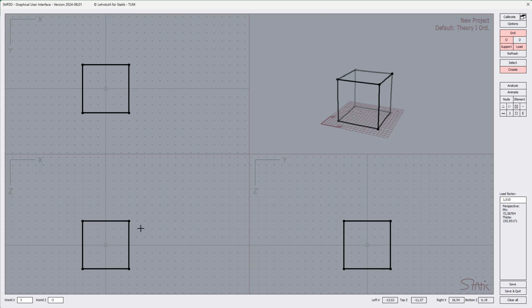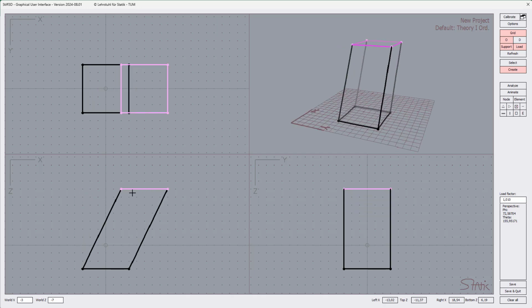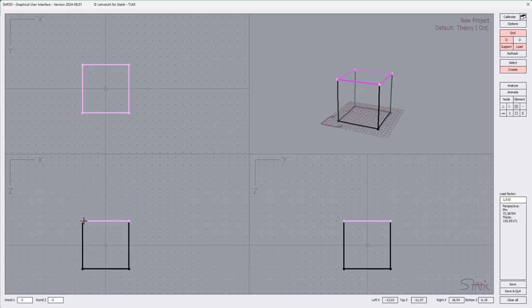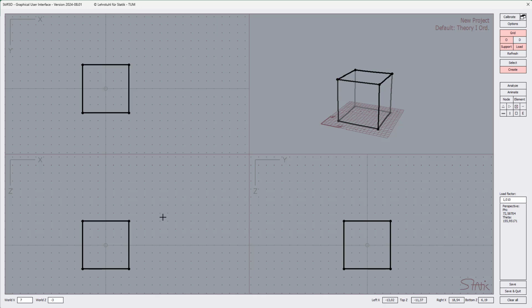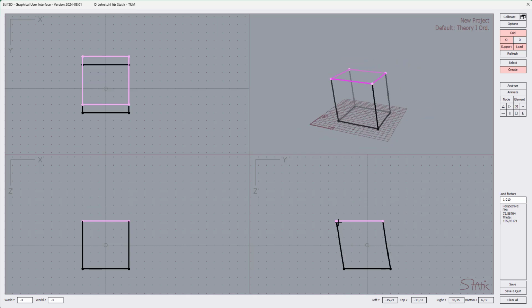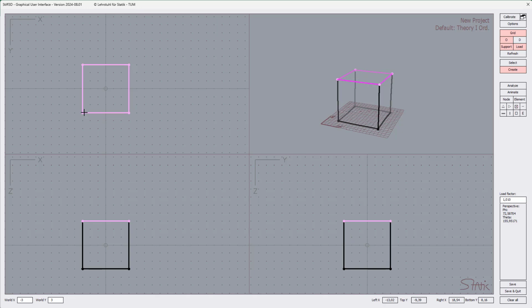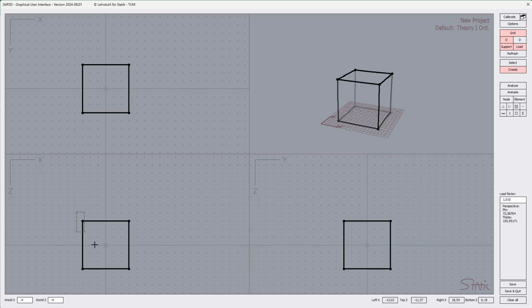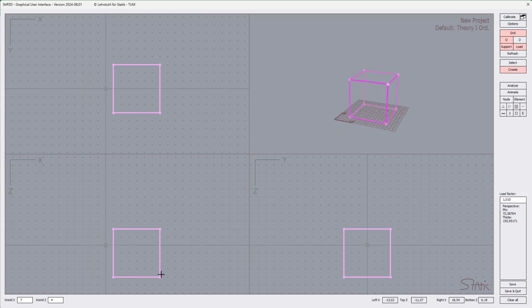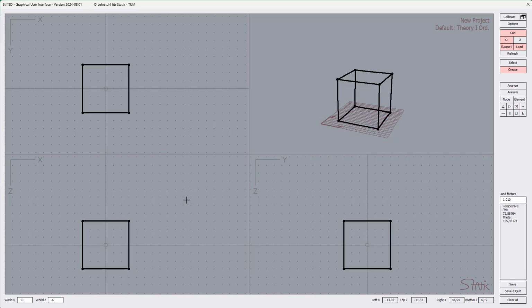We can of course select more than one node by the rubber band, and if we now press the left mouse button again at one of these nodes, you see that we are now simultaneously moving all of these selected nodes, and we can do that of course within all of the other views, or just proceed here as an example. So by that we are able to move the object into the place where we would like to have it, or selecting all of them, I think it's straightforward that you understand that we are now able to move the complete body as a whole.